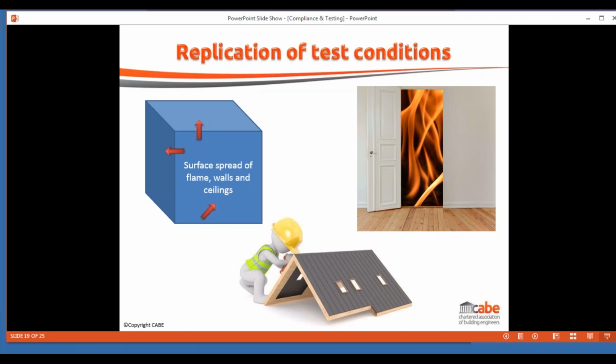But obviously in a real fire situation, a lot of those fires that the door is holding back in the very early stages are not a furnace firing at full blast. They are slow smoldering fires that start over a considerable period of time. So actually in reality, a lot of fire doors might last a lot longer from the ignition of the fire than would be indicated by a fire test, where it's looking at a slightly more advanced fire.